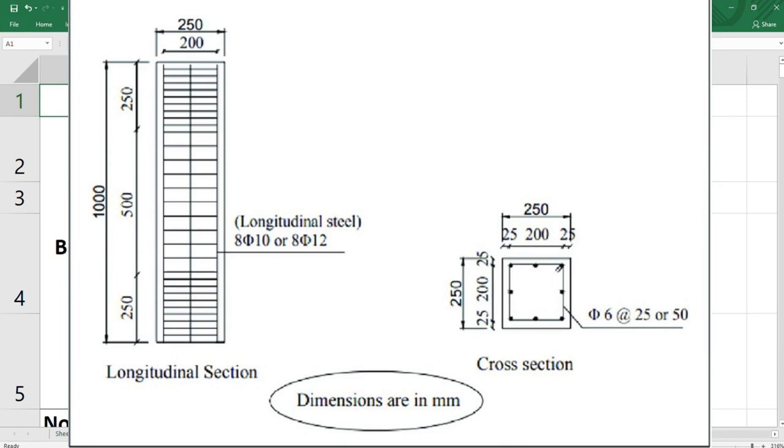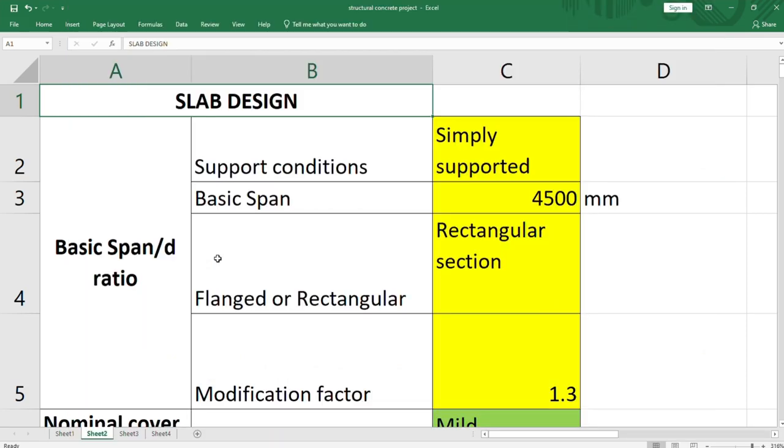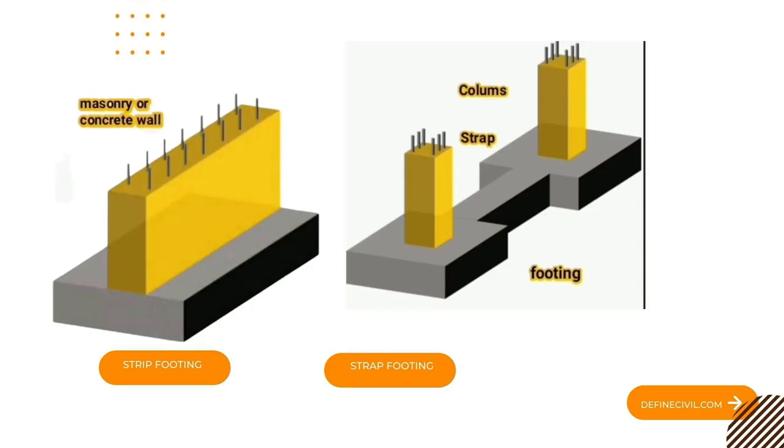Then from there you go to the foundation, where you design a foundation that will carry this load, distributing it to the ground safely. Then you need to check, of course, the geotechnical part of the soil to see whether it can really bear this load, while choosing the best type of foundation that you recommend.